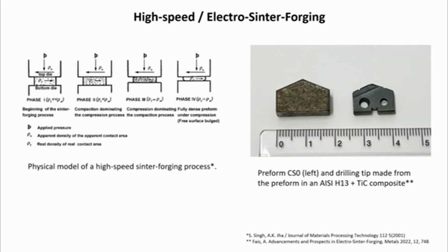Many solutions of sinter forging problems have been reported on the various technological aspects of industrial processing of sintered material. In the high-speed sinter forging process, the surface of the workpiece is distorted and takes on an impression of the die surface. Therefore, the actual contact area, as far as the specific cohesion of the surface is concerned, is not negligible. Friction conditions in forging are essentially different from the sliding friction in machine parts. The relative velocity between the workpiece material and the forging die surface, together with a high interfacial pressure and deformation, will create the condition essential for adhesion in addition to sliding.